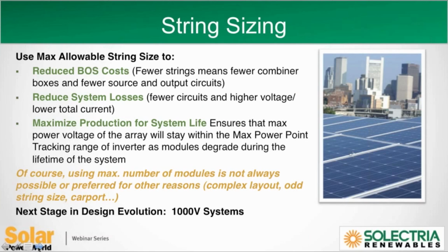Now, when you do your string sizing, many times you'll get a range of allowable string sizes. That's not to say that every time you need to use that maximum number of modules per string. There are always going to be unique situations, and other design considerations that are all forming the design into its final form. Sometimes the maximum string size is an odd number.